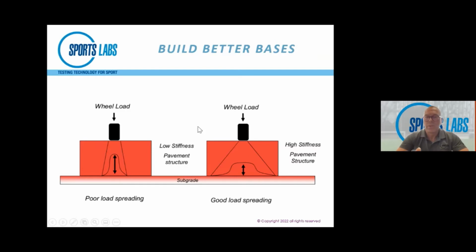Essentially we're not looking to load an artificial field significantly after it's been built, but sometimes you need a good base just to build the field. So if you're given a site which has got some issues with soft materials, or it may be reclaimed materials, or it may even be an old tip, then you need to put a decent base in to even get the field built in the first place, just to support construction traffic. So the base can be there for many, many reasons.